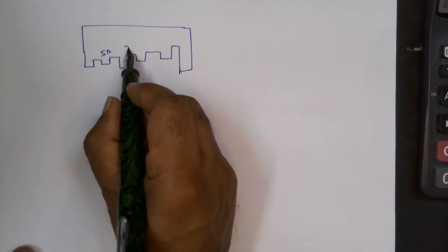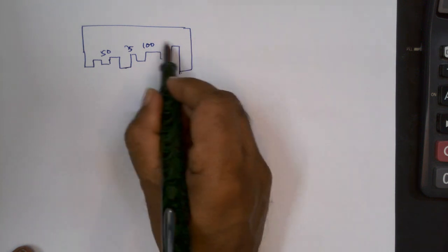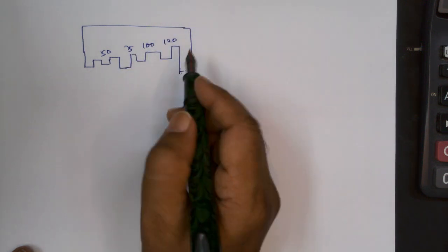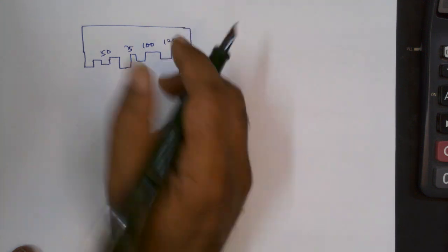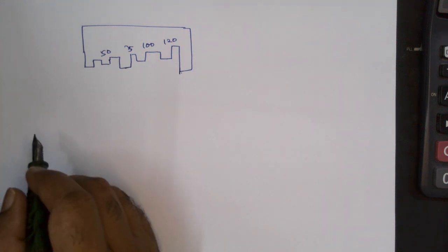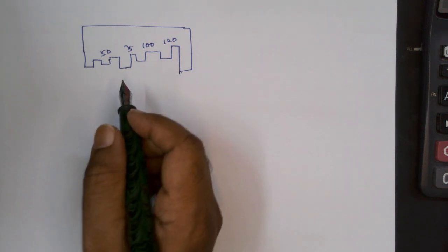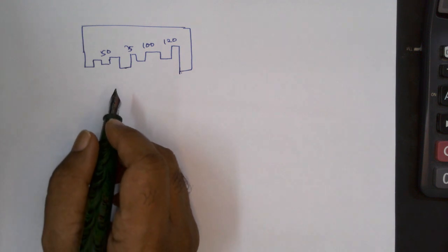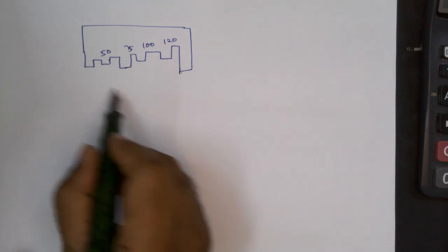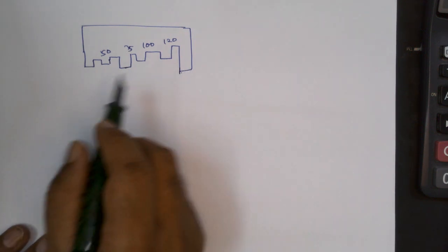This is 75 micron. This is 100 micron. This is 120 micron. So based on the depth, it will have a certain value here. Okay. Usually this device is dipped into the wet paint, and until the two end prongs are pressed hard against the substrate.